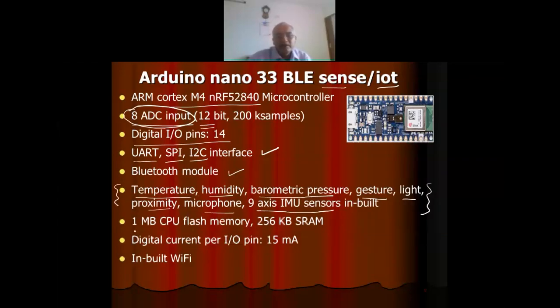It has 1 megabyte of CPU flash memory where your program will reside. 256 kilobytes of static RAM is available. And digital current per input output pin is 15 milliampere. So you have to keep this in mind. If you have a larger current, then you require some kind of driver circuit.